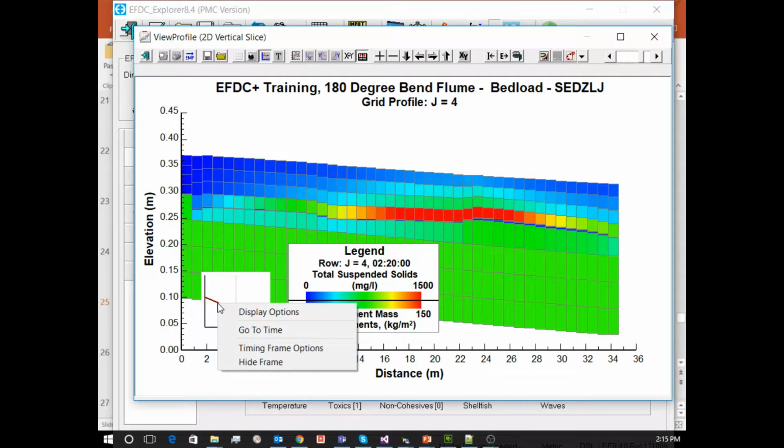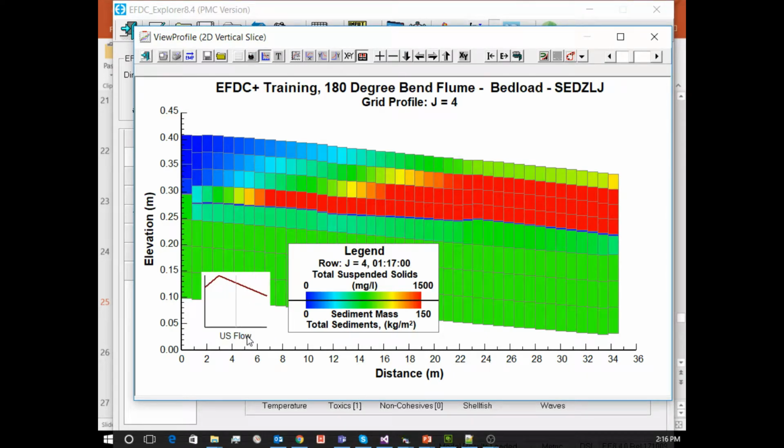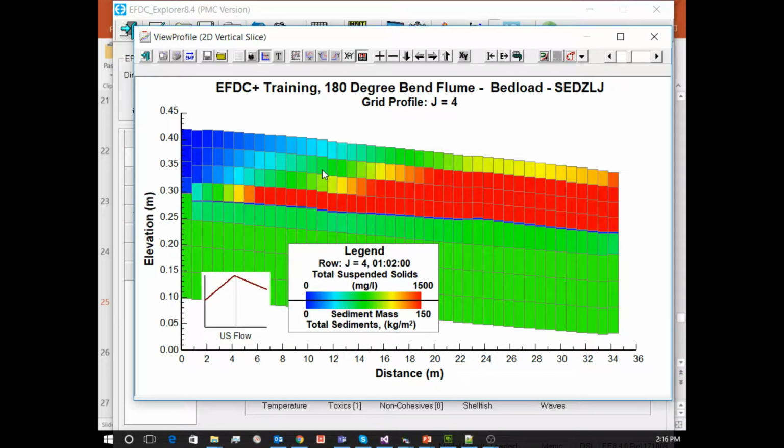We'll do this afternoon with the Chuck Coop, but it's a quick way to jump to like the hydrograph peak or the hydrograph recession limb. So you see your hydrograph, and you just right mouse click and say, go to that time, and it takes me straight to that time. Now in this case, it's somewhat trivial. Like here, if that was my peak, this is only a 1 hour period. And again, it's all user defined. So I told it 1 hour, and I'll show you how to do that. But if I want to go right to the peak, I just go to the peak with my mouse, right mouse click, go to time, and now that's the peak time. These are just ways to get around temporally in your model.